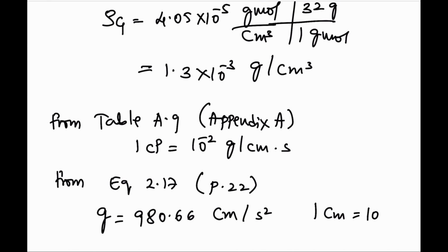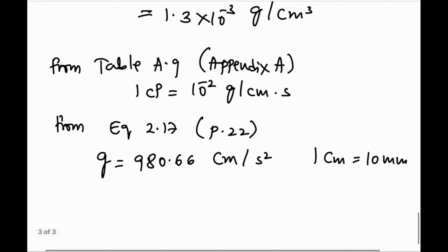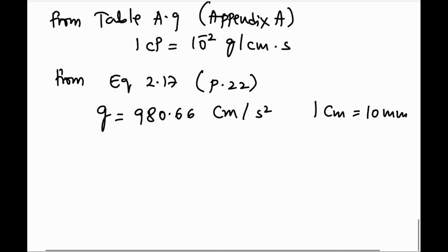Now the parameter values and conversion factors can be used to calculate the dimensionless groups in the equation. Let us first convert into consistent units, because viscosity and bubble diameter are all in different units. The viscosity mu is 0.89 centipoise.